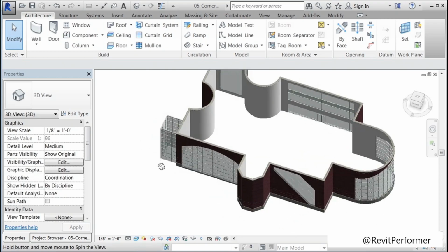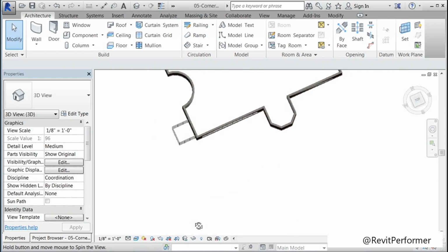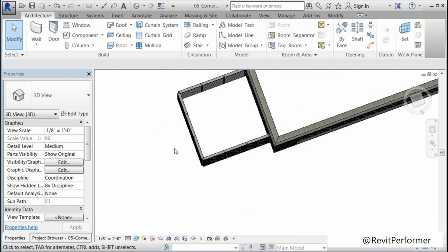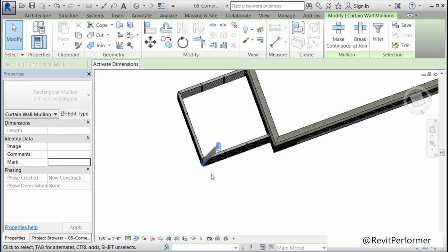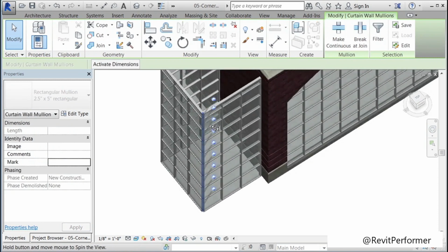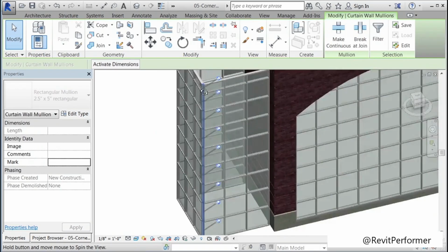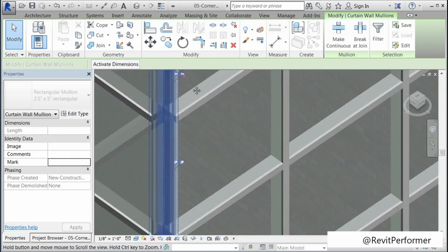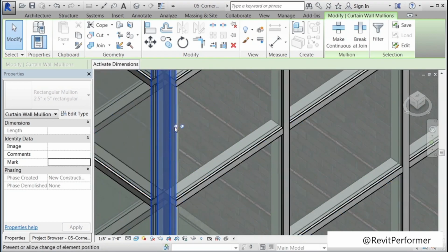I'm going to pan around, so I'm looking almost straight down at it, but not quite. Now what I'm going to do is, with a box, I'm going to go ahead and pick a window right around those interior mullions. Now I'm going to scroll around so I can see the pins. The problem is we need to unpin each of them. So zoom in and unpin them. The taller the building, the more tedious this is going to be.